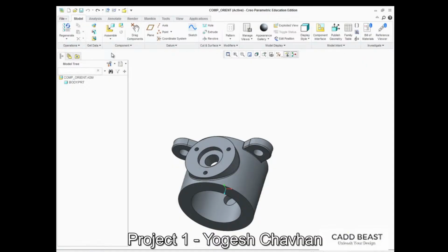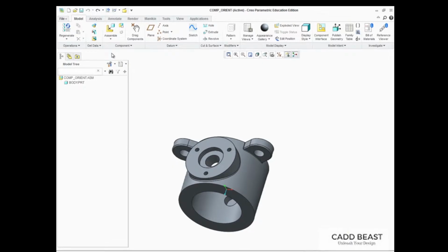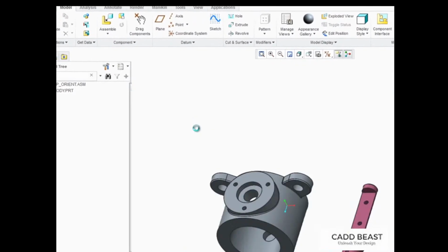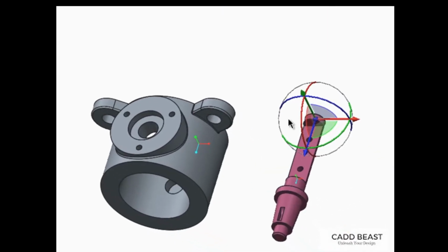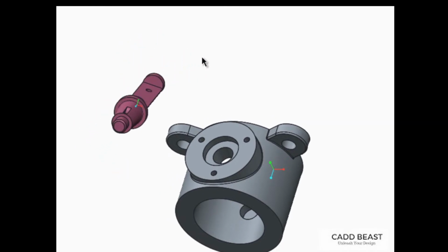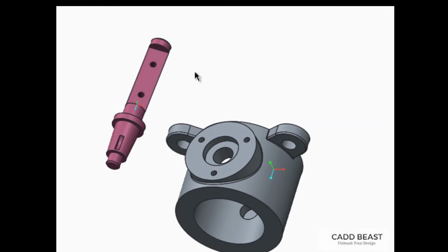Creo Parametric's new 3D Dragger interface has been added to make the process of orienting a component during the assembly process simple, fast, and intuitive. You'll see it as soon as you add a component to the assembly. Of course, you can still reorient a component by pressing the Control and Alt keys while using the mouse buttons to pan and spin within the assembly.